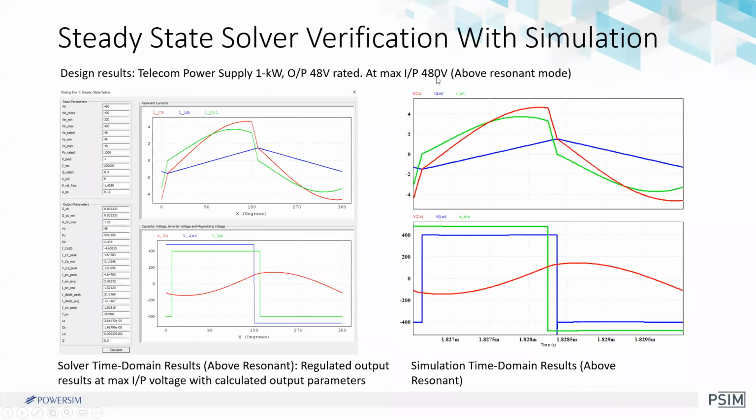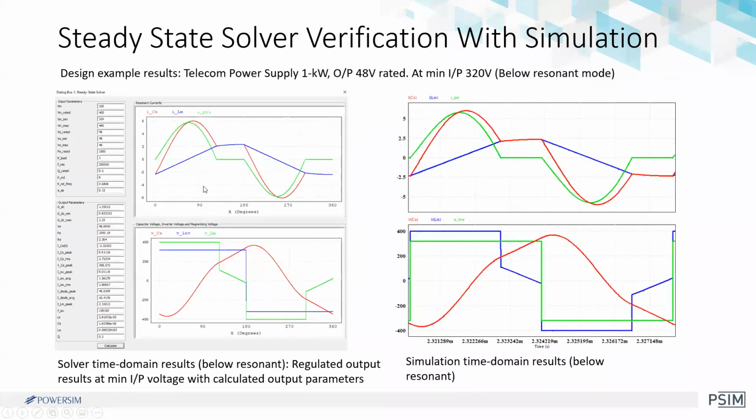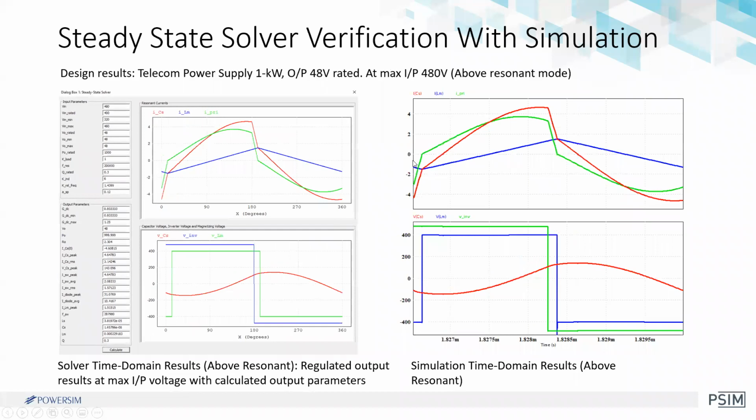At maximum I've shown that, of course, below we wanted to go for more gain, so we go below resonant to 6.8 and there's a DCM, you can see right away. So 1.25 gain we wanted, and then when the voltage went above the nominal, for 48 we have to get the DC gain lower than 1.